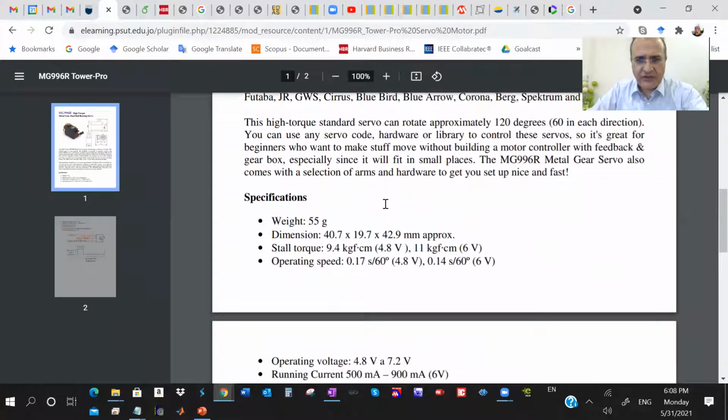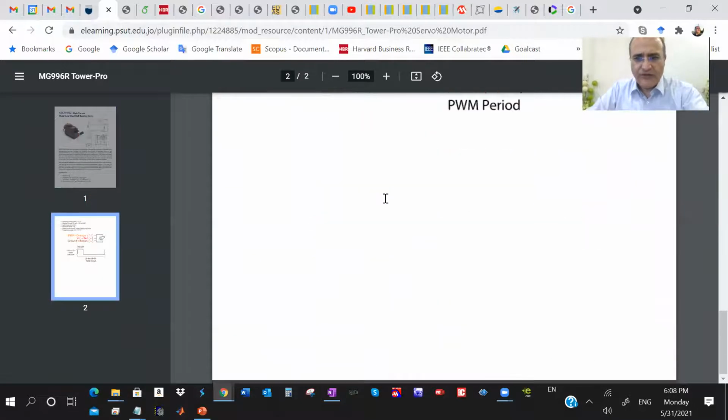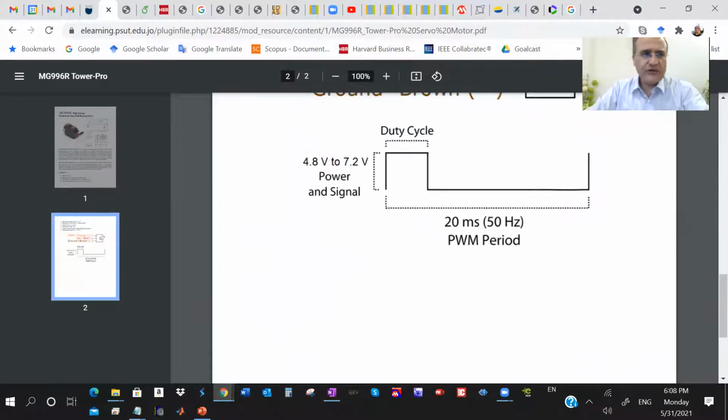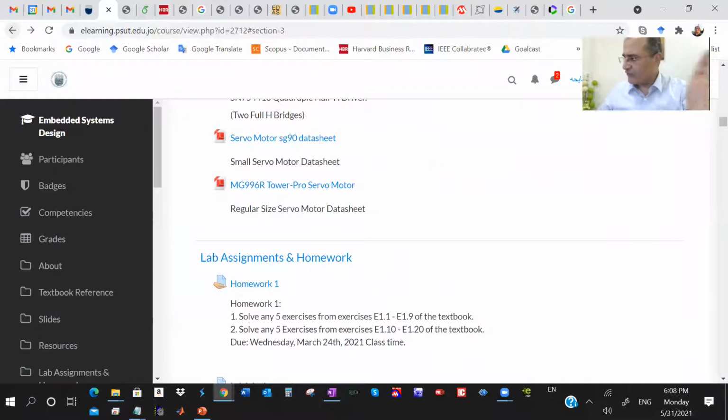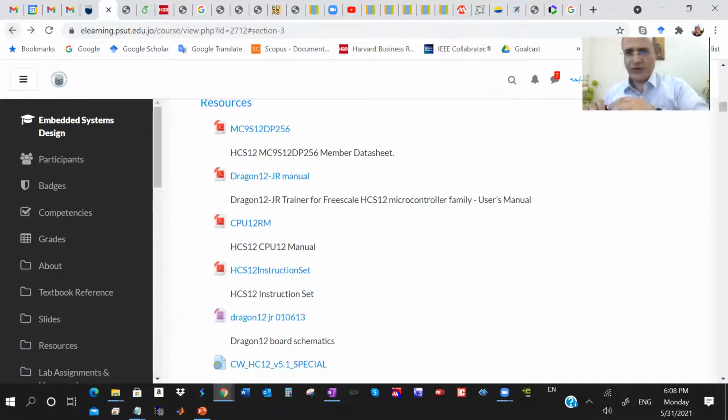Oh, is this a speed or what? Some of them are angular servo motors. I asked Mahmoud to give me one that rotates 360. Some of these can rotate 45 degrees, 180 degrees, and you change the pulse width to change the angle they're at. Some of the servo motors are 360, and the pulse width in that case will control the speed of how fast they're turning.